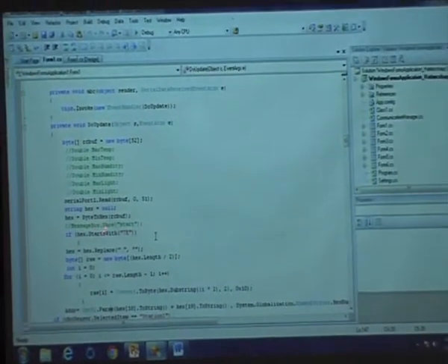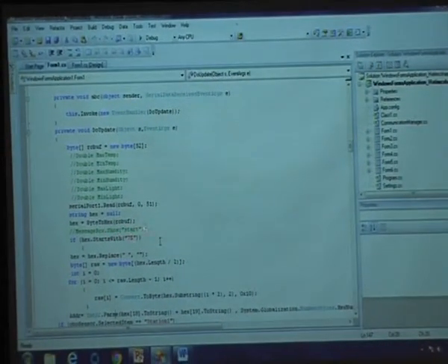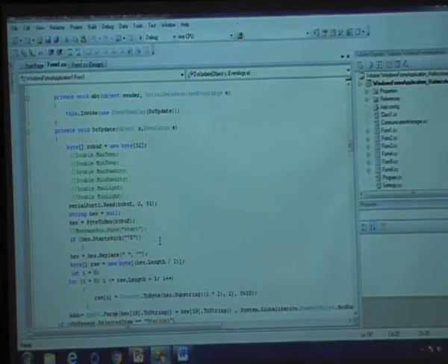Then the next statement is: whatever you are receiving in terms of hexadecimal values for that X value, the serial port values are received in terms of hexadecimal. So what you write is if X dot starts with 7E, it clearly states that the frame starts with 7E. Now this is one logic I am just showing you which can be executed and which can show you the values over here.